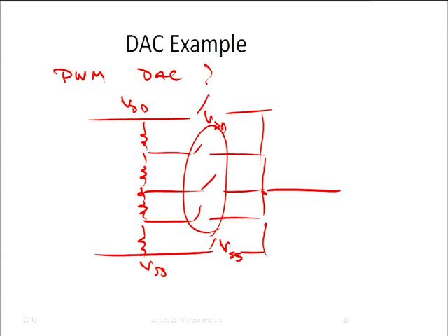All right. So yes, it's simple. I guess the advantage of this is that it's simple, and I actually used one 30 years ago when I was in high school. I had to build something, so I used one of these, and I liked it because I could easily understand what was going on. I've seen them also used in video outputs. Inside there is the video processor, which of course produces digital information, and then the VGA port is actually analog, so you need to convert that to an analog number, and that's done with the DAC, and very often they use DACs that look like this.